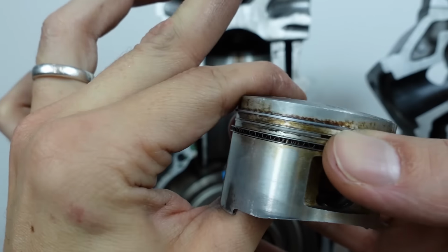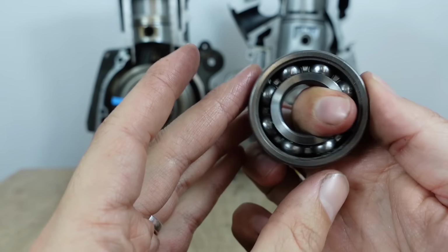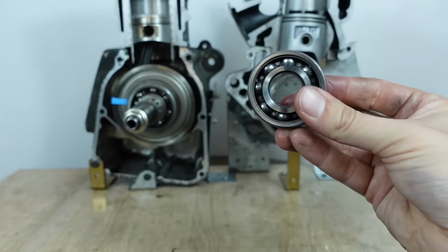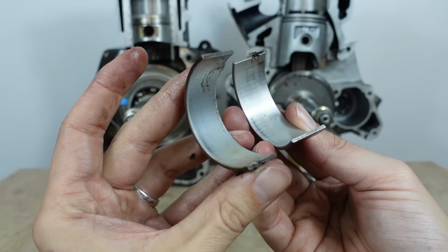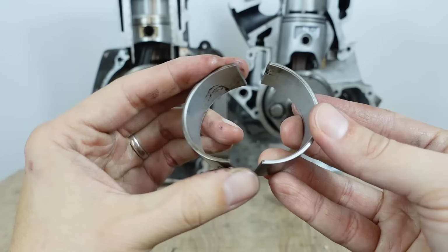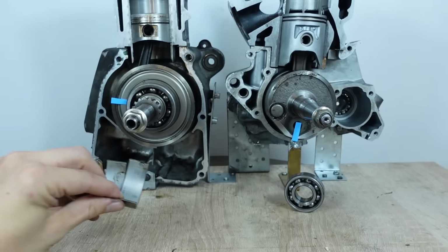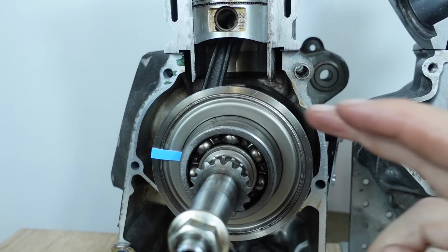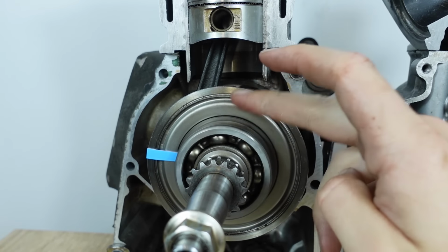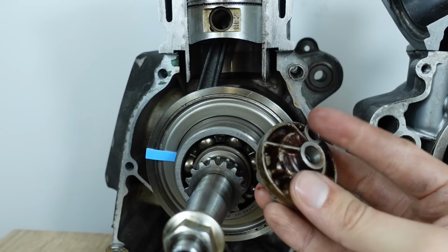The lack of consistent lubrication is also why 2-stroke engines often use ball bearings and/or roller bearings as their rod and crank bearings. Ball bearings are more expensive and require more space than plain bearings, but they're far more resilient to poor lubrication environments. On the other hand, most 4-strokes can use plain bearings, which are very small and inexpensive and which together with a good film of oil offer excellent load bearing capacity and higher shock resistance. But our example 4-stroke engine actually uses ball bearings too. The reason is that this is a very compact and inexpensive engine which has a very small oil pump that isn't able to provide the kind of lubrication that oil pumps on the larger, more advanced 4-strokes can.